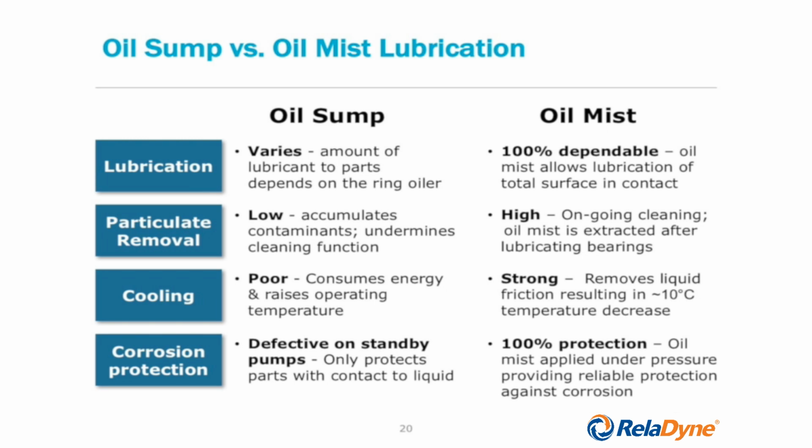And as a result, the air that's in the bearing housing is now going to contract, and the pressure goes down a tiny bit compared to atmospheric, and the atmospheric air pressure is overpowering the seal area, and we are pushing moisture from that outside atmosphere into the bearing housing.